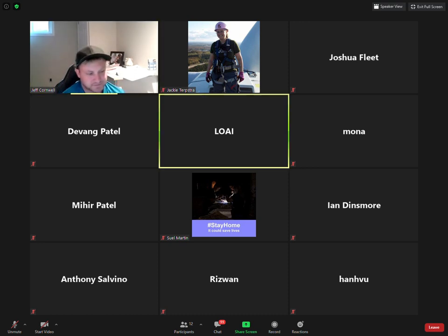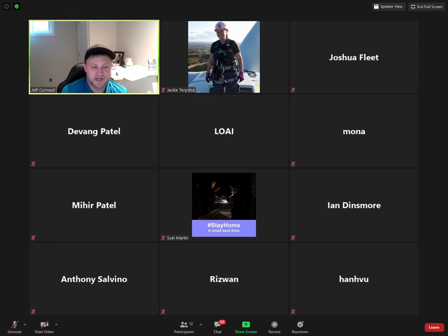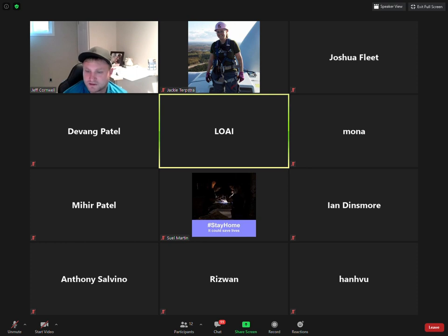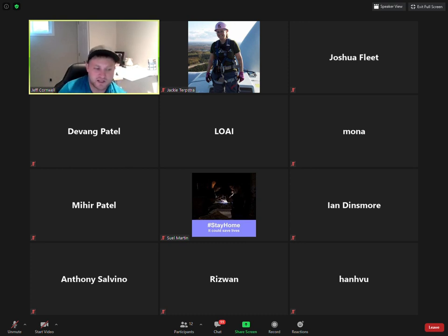Yeah, we will learn from each other, or learn from the things that happen during these classes. For the pocket length, is it considering the taper length or just the lane itself? Just the lane itself. Okay, and also the dual entry in Vistro, does that mean that when I click yes or check it, I'm allowing compatible movements to work at the same time, or what's the meaning of that? Yeah, exactly. You described it perfectly. If you click dual entry for eastbound and westbound, it means they both move at the same time.